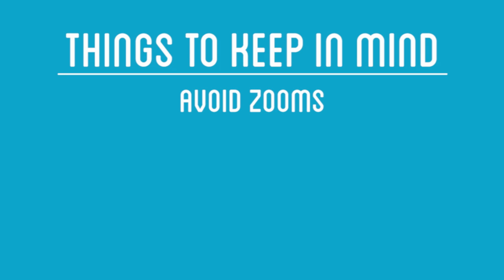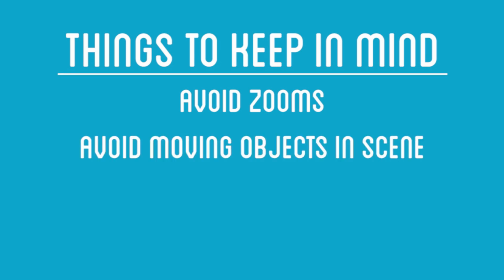It's more difficult for After Effects to track, and you want to make this process as simple as possible for yourself. Don't have a lot of moving objects in your scene. After Effects 3D Camera Tracker uses motion based on your camera movement to calculate what the virtual camera it's going to generate looks like. If there are a bunch of moving cars or swaying trees or people walking in your scene, After Effects has no way of knowing that those are actually people or cars or trees. It just sees the pixels as movement and will mess up your track, thinking that those objects are part of your static scene. It's okay if you need things to be moving in your scene, but you'll potentially have to mask those out so that the tracker only focuses on the scene itself.